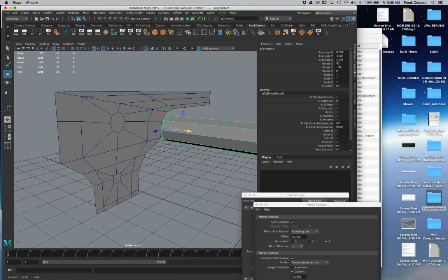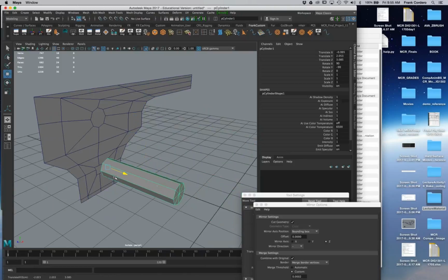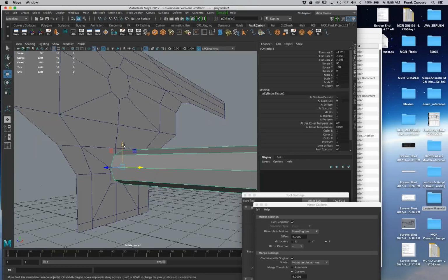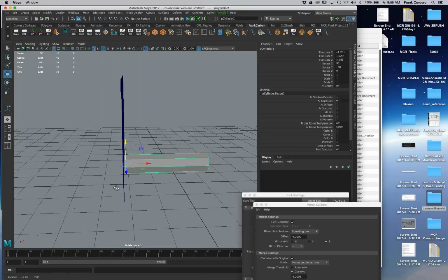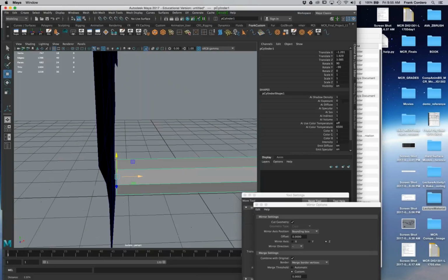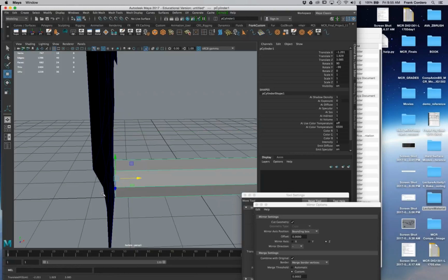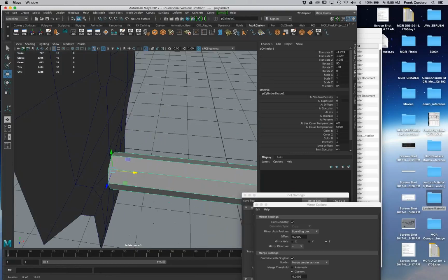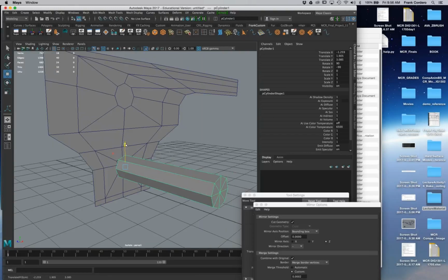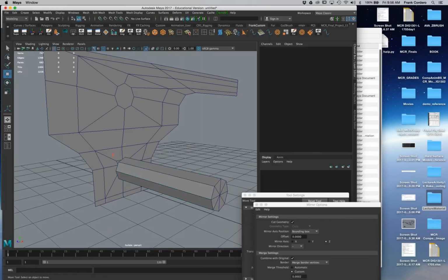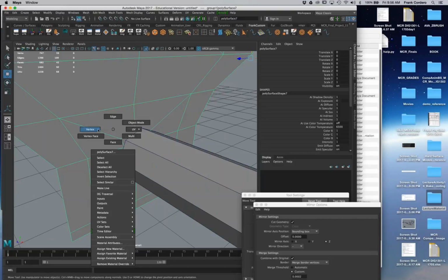See what I'm doing? So now I'm going to do the same thing down below. I'm going to put this guy in the area where I want the hole to be as well. And I already know it should be flush, but if it ain't flush, oh, I guess I moved it already. So I'll just hold down the C key. Whoops. See? Cool. And now I'm going to do the same thing. I'm going to make the hole in the middle there, and then select vertex.